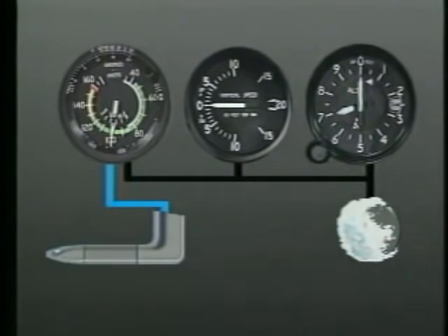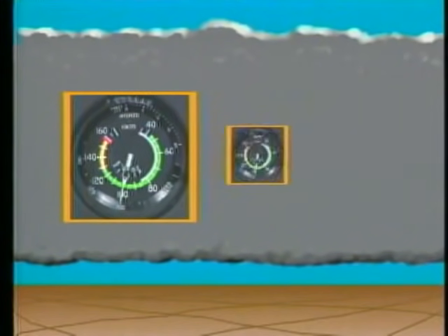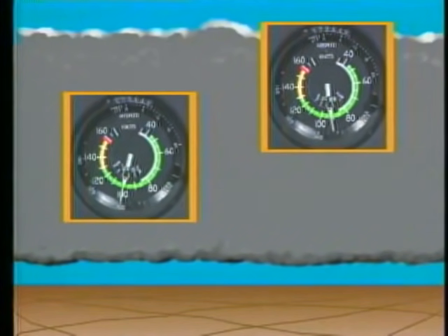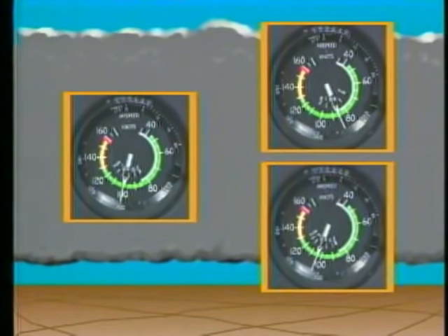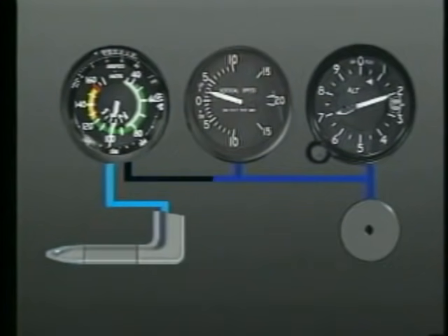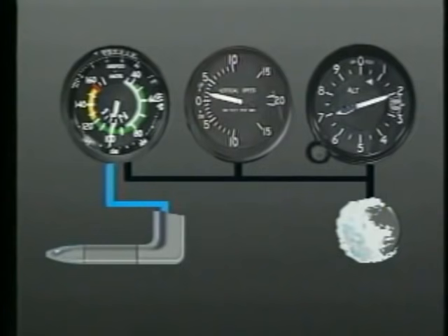If the pitot tube remains open but the static system becomes blocked, the airspeed indicator still reacts to changes in airspeed. However, the indications are not correct. If you're operating at a higher altitude than where the system became blocked, then the airspeed reads lower than it should. Below the altitude, the airspeed indication is higher. The greater the altitude change, the greater the error. If the static system becomes blocked while you're changing altitudes, the altimeter freezes in place and the VSI returns to zero. If this occurs, you need to find an alternate source of static pressure.